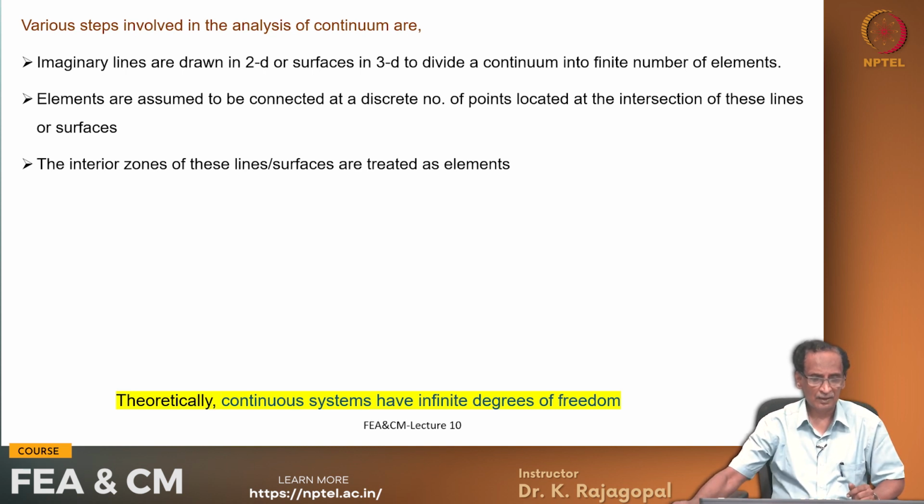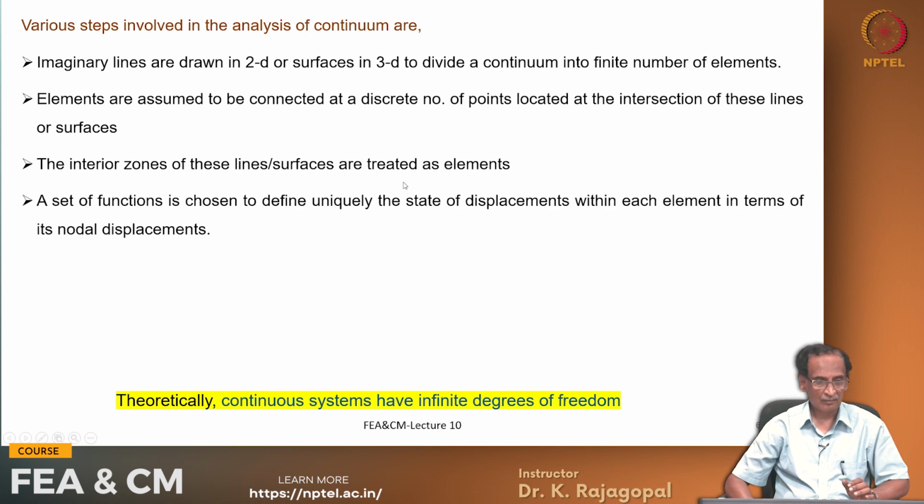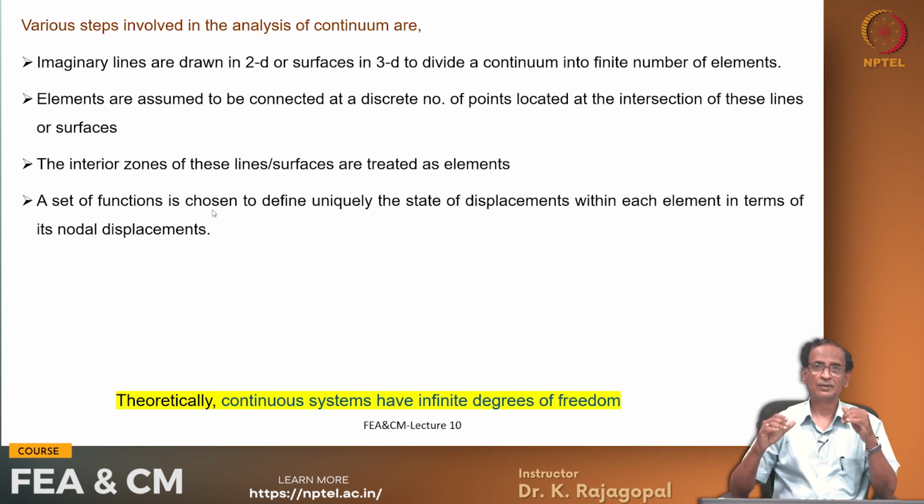And the interior of these lines or surfaces are treated as elements, and then we choose a set of functions to describe the variation of the displacements within each element, because once we define the nodal points, we know we are going to solve for them, but once we get the displacements at these nodal points, how do we find the displacements in the interior of an element?